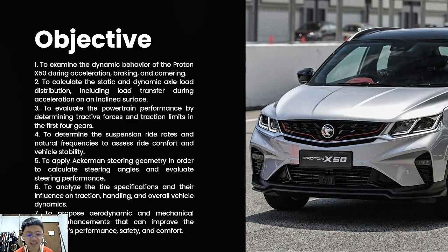These are the 7 objectives. The first one is to examine the dynamic behavior of the Proton X50 during acceleration, braking, and cornering. The second is to calculate the static and dynamic axle load distribution, including load transfer during acceleration on an inclined surface.